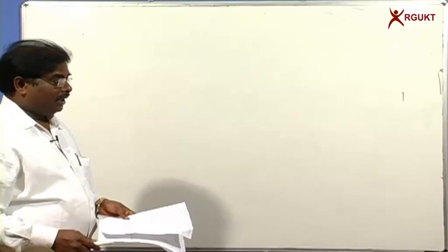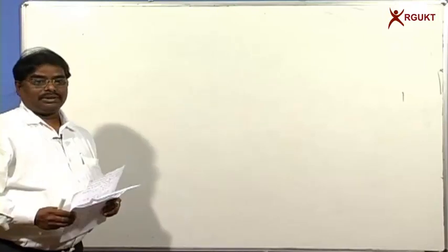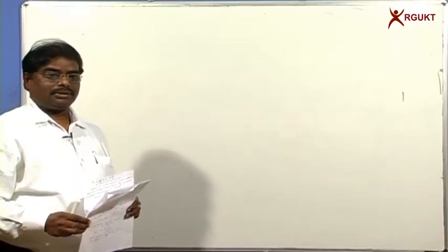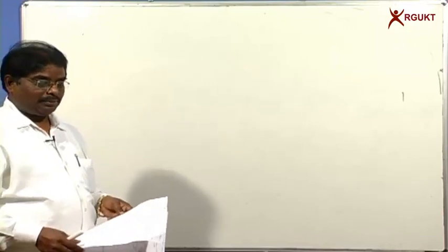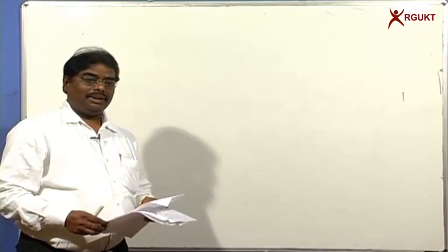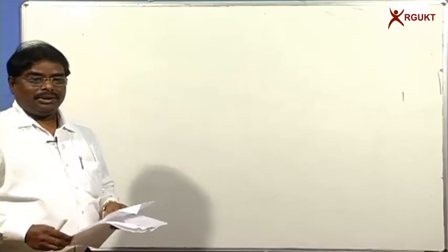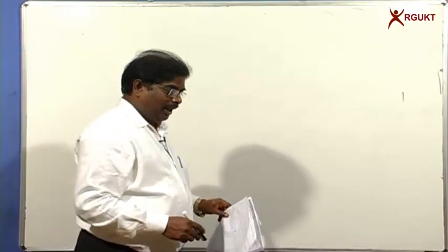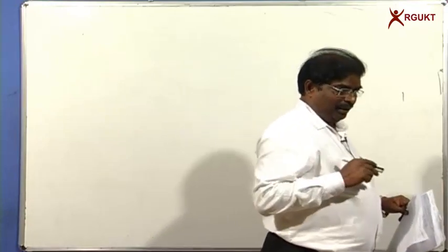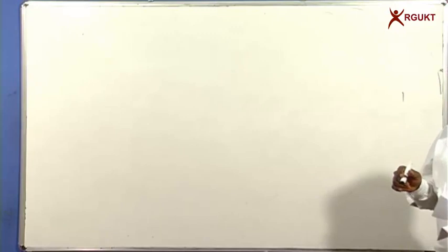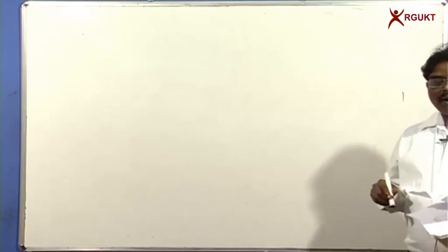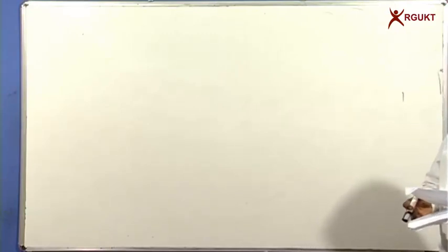Continuing the previous class, we have discussed already about the fluxes, how to calculate the flux. There we discussed the two types of fluxes. One we called the N-type flux, that is with a stationary frame of coordinates, and the other is the J-type flux, which is relative to some sort of a relative velocity, maybe based on the molar average velocity or maybe a mass average velocity.